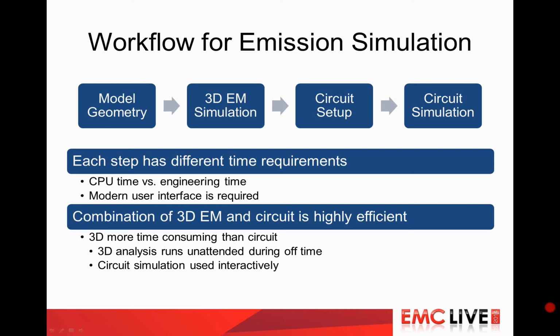And as the title of today's presentation is about the emission of PCBs, I have two methods here: the time domain based on the finite integration technique, and the frequency domain based on the finite element method, which have been shown to be the most efficient methods for running a 3D simulation of a modern day PCB. And both methods have quite different properties, and they complement each other very well.